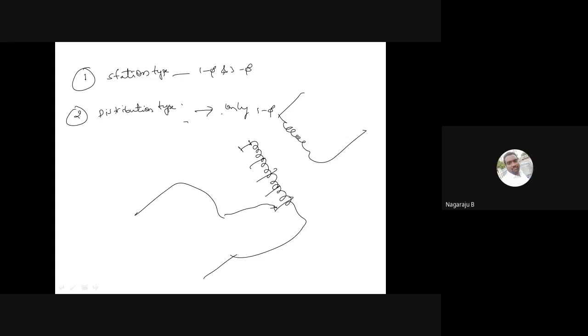The control mechanism provides the control of voltage level and bandwidth. Further, it provides the ability to adjust line drop compensation by selecting resistance and reactance settings. And how you control it: the rotation of the primary coil in the induction type of regulator, and a tap changing transformer in the step type of regulators, are controlled by the voltage regulating relay.